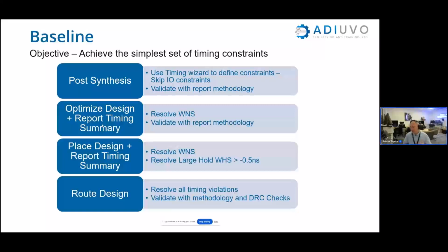But we're not just going to click the button, like I said, and wait for the bit stream and then start trying to do some debugging. What we do is the synthesis first. Once the synthesis is done, if the timing constraints aren't already defined, we can define the timing constraints.